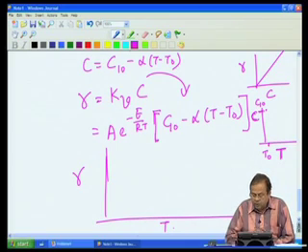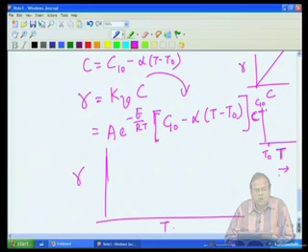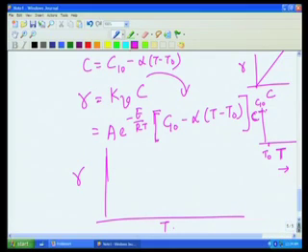Now, what happens as my temperature increases? Since it is an exothermic reaction, the concentration decreases in a linear manner. So, this is how concentration changes with temperature. Let us try to see how Kv changes with temperature, and we know this. There will be some increasing function like this, starting with T naught to a higher value. What we are interested in knowing is how the product of these two values, Kv into C, looks, because that is nothing but the rate.